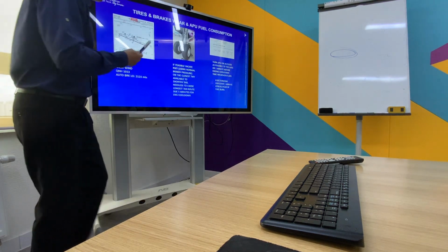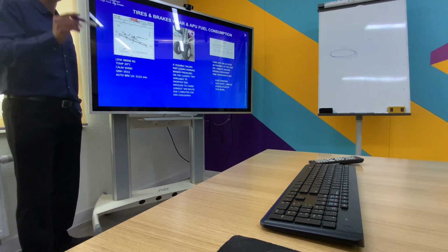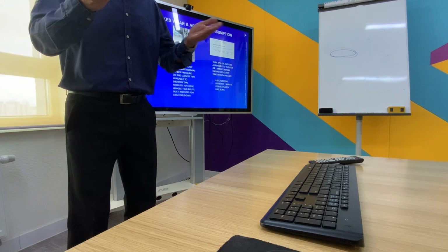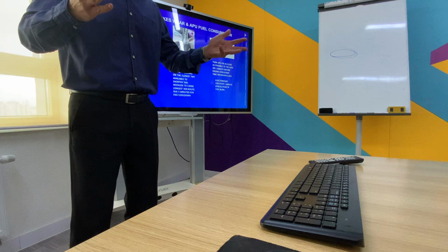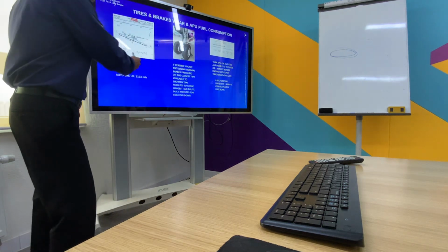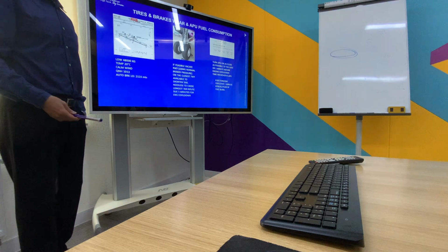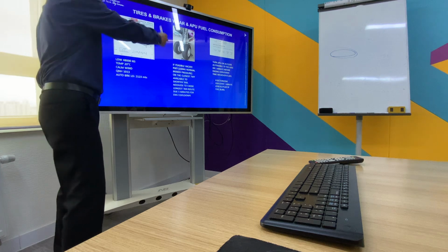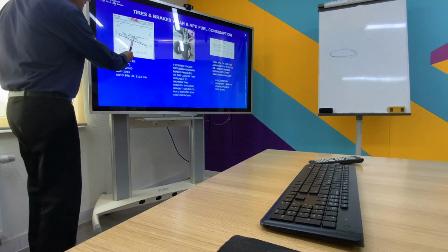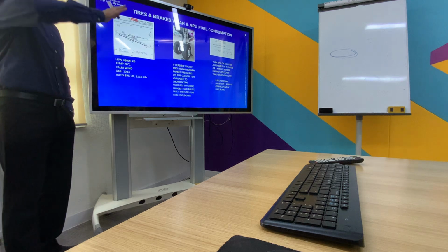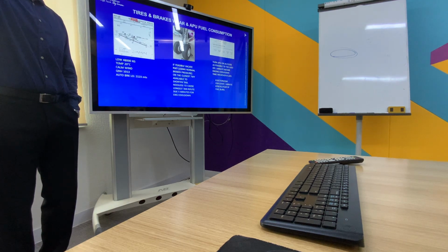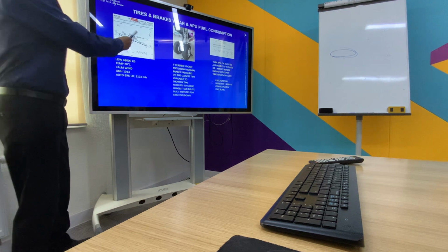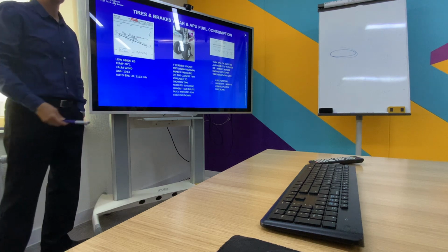If I don't have any restrictions at the airport on staying at the gate with engines running, because of noise or something like that, you may vacate on Charlie, park at the gate, and wait 5 minutes there. You are saving tire and brake wear. Why would I choose to vacate on Alpha, a long taxi? You know what I mean? It's because of the engine. There's no reason for that. You are wearing tires and brakes unnecessarily.